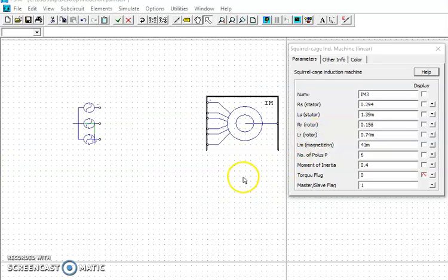If you take a look at the PCM, this is the initial setting of your device, your motor. You don't have to change any of this except the number of poles. Once you complete your experiment, you can change the number of poles into either 4 poles, 2 poles, whatsoever, which is an even number. Then you rerun your experiment.